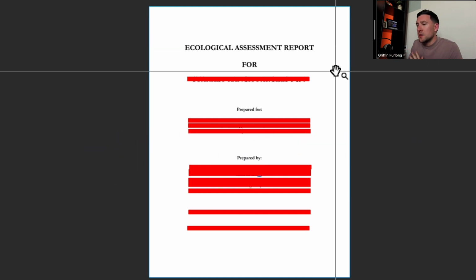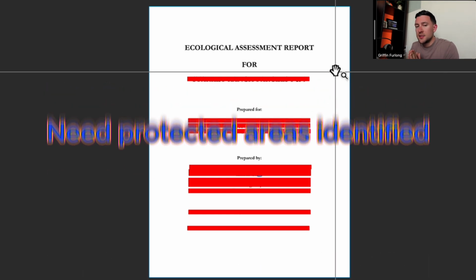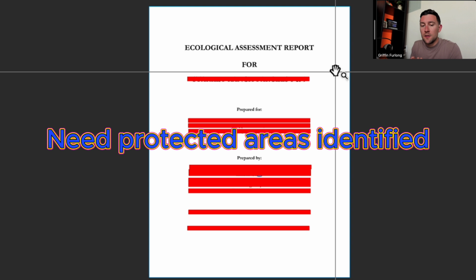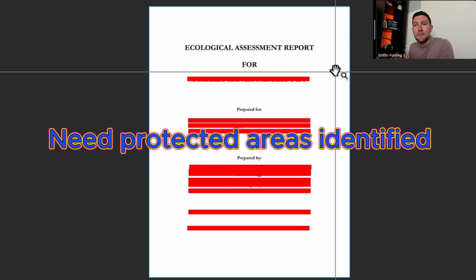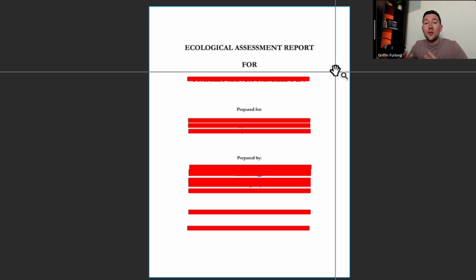As far as the land development engineer's perspective, the most important thing that I can gather from this type of environmental report is definitely the existing protected features, for instance, like a wetland or a ditch that may be protected, or perhaps there might be a wood stork nest or some sort of eagle's nest that's protected, and then we won't be able to do construction for a certain period of time. All of these things really matter as we develop our schedules and try to permit these sites.